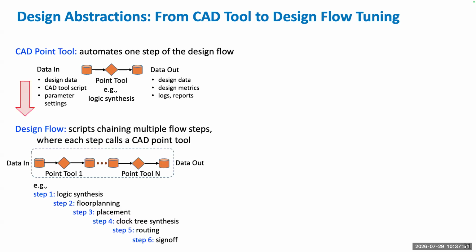A full design flow is then going to be a set of steps, and it doesn't have to be these exact 6 steps, but usually it's like these where we have logic synthesis, floor planning, placement, clock tree synthesis, routing, sign off. This is a linear progression example. You could make this in many ways. You can add steps, remove steps. You could loop steps for optimization passes, but thinking this, now you can think of a more solidified higher level abstraction as a tool flow pipeline.